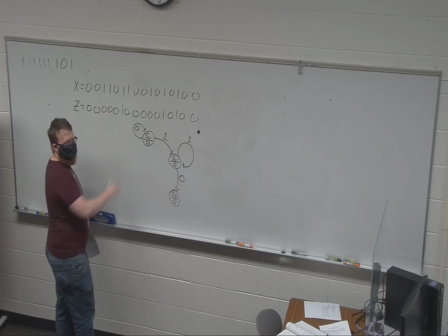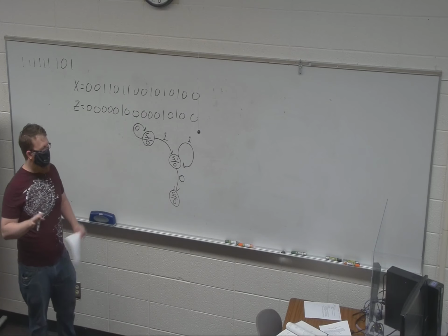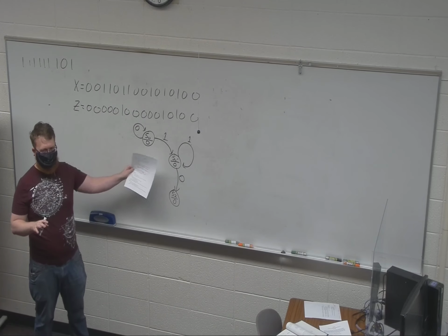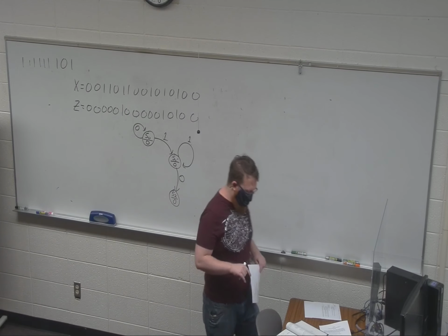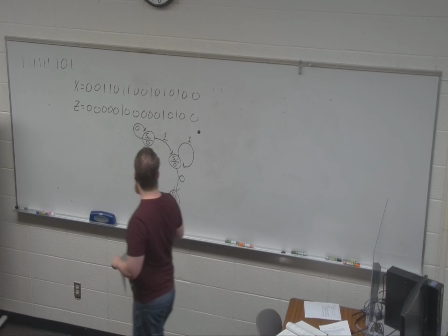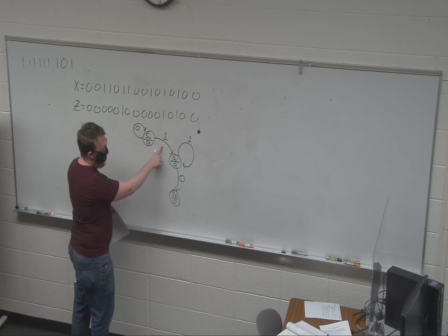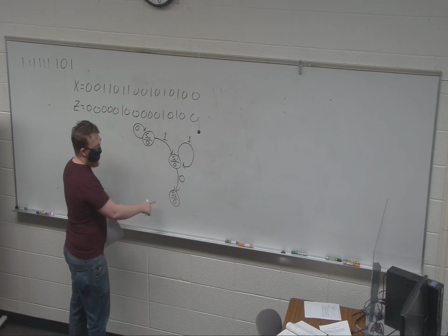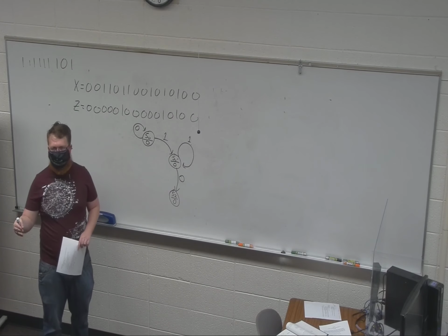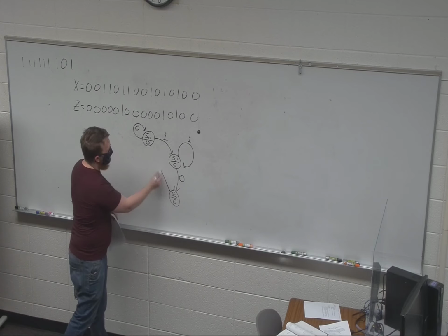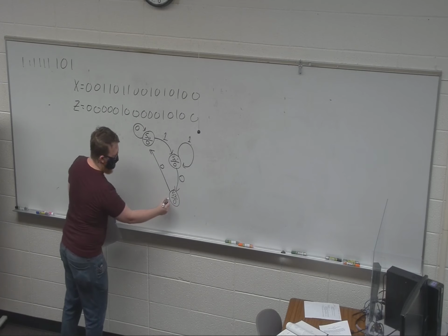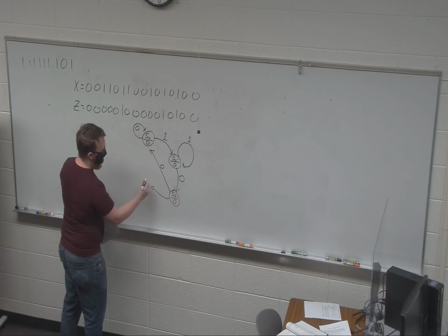Where you have the state and the output in that little bubble. Because you're not doing it on the transition, it doesn't care about what the input is, it cares about what the state is. So if you're in state 2, which has seen a 1, and now has seen a 0, the two things that can happen: it can see another 0. What happens? So it's seen 1, 0. Yep, we're going to go back to state 0. If it sees a 1, we're going to move on to another state.